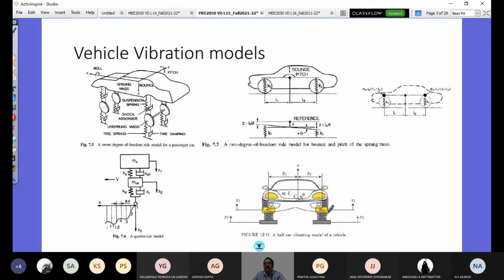And when I account for the unsprung mass also, that is not going to change your result. It becomes more and more realistic as you eliminate the assumption of wide separation of frequencies. In this case, we consider it and you would be able to carry out the analysis. However, if you look at the bounce, pitch, and roll, this is the order of annoyance.